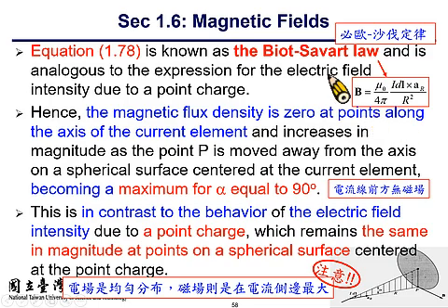All right, so this equation is known as the Biot-Savart law, which can be an analogy of Coulomb's law, so its application is similar. So for a very short piece of current, which is dl, and the magnitude of the current is I, the magnetic flux density is proportional to the inverse of the distance r, and is related to the material property mu sub 0.